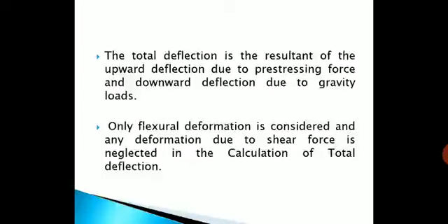So similarly, in case of deflection also, the prestress force produces an upward deflection which tries to counterbalance the deflection produced by the loads. Hence, we can see that the PSC elements will undergo a lower degree of deflection as compared to the RCC members. This permits the use of PSC members for a long span, and also we can have slender members in PSC as compared to RCC.